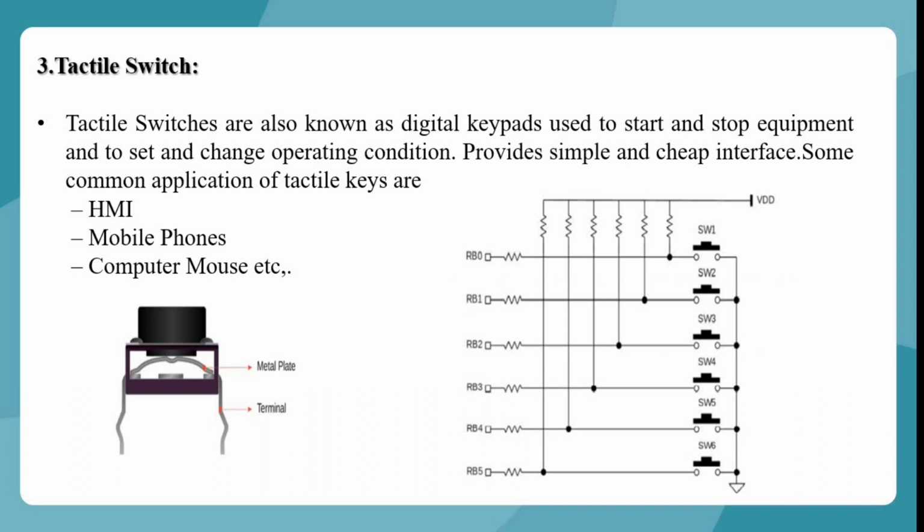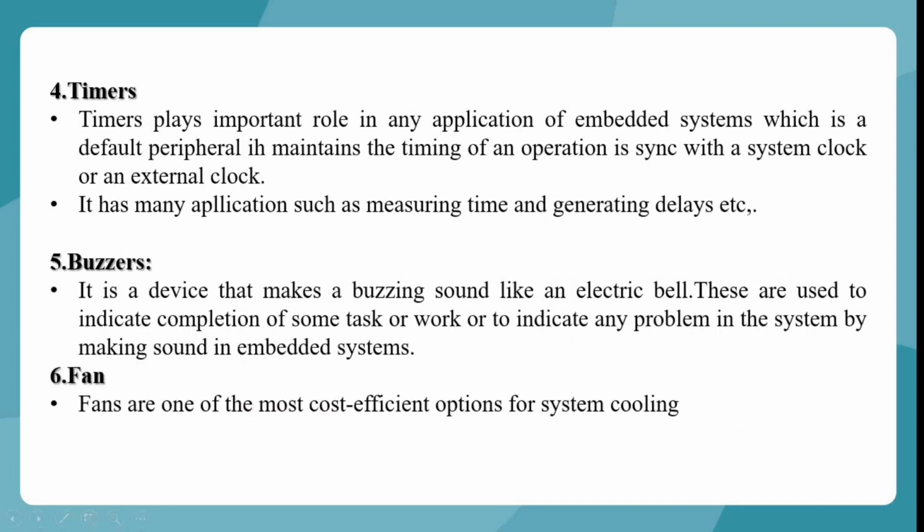Actually, in this project, we have used tactile switches to navigate between the options, and to power on the washing machine, we must press a switch. So in that case, we have used tactile switches, and this is the schematic diagram of tactile switches in the PIC microcontroller.